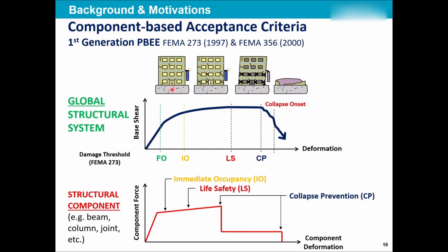For every single component that the building has in a simple pushover using SeismoStruct or OpenSees, for each component there is a defined behavior curve, like a hysteresis curve, but just monotonic, just one side of it. Then it combines all of those, and at the end, the output that you see is actually just one single pushover curve for the entire building. You are able to see this curve for every single component as well.